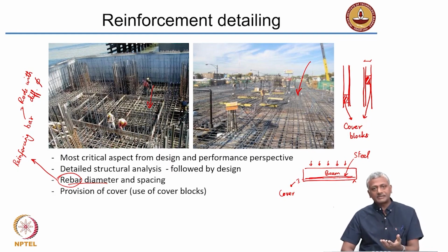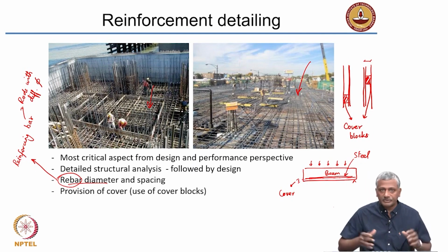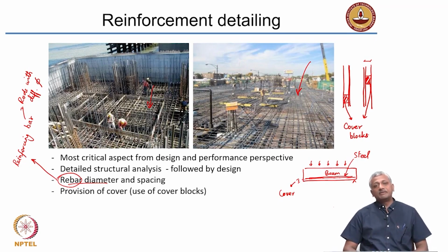Again, if you go through design practices, you will understand that the thickness that you want to provide as a cover is determined by the kind of environment that the concrete is in. For example, if your concrete is in a coastal or marine environment where it's going to be subjected to a very harsh aggressive condition, because you know that there's a lot of chlorides and they can cause the corrosion of your reinforcing steel, then to ensure that the steel does not corrode in the lifetime of your structure, you need to provide a thick enough band of concrete around the steel. That's called the cover, and that cover in most marine conditions, for example, for structures like columns which are standing in seawater, could be as much as 75 millimeters.